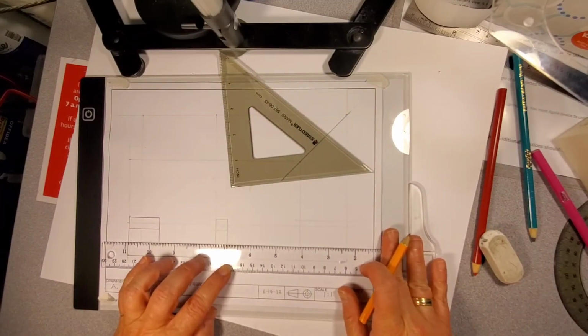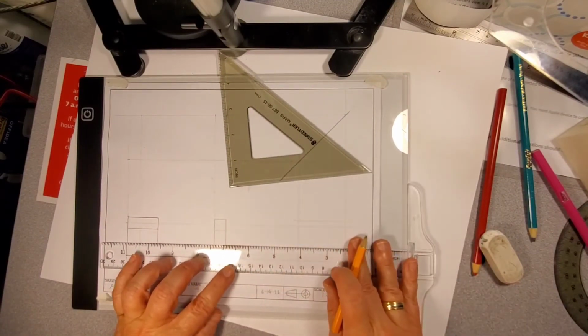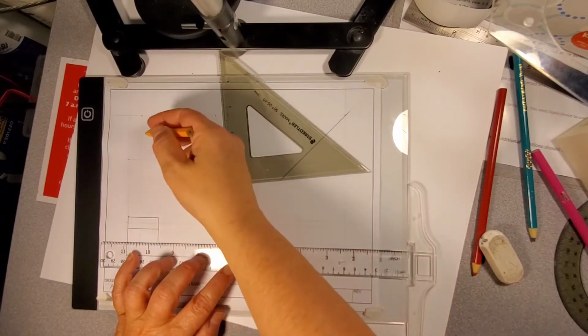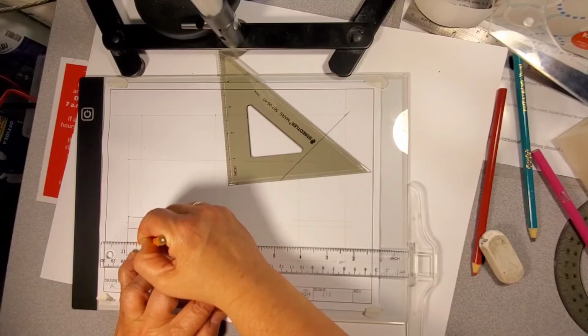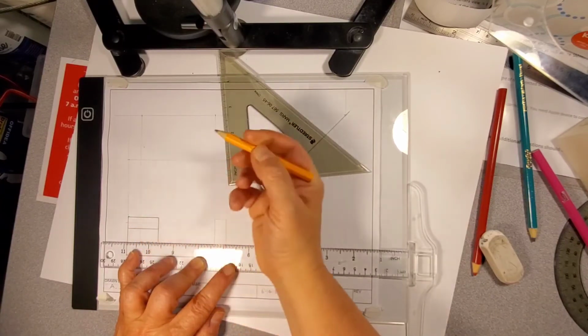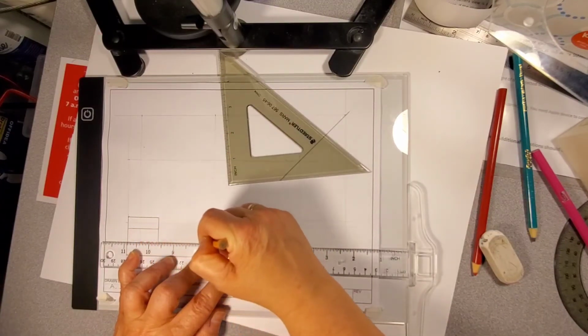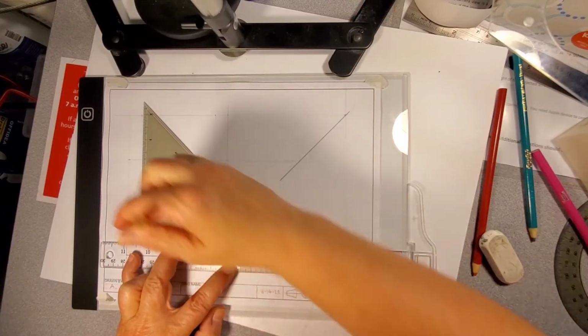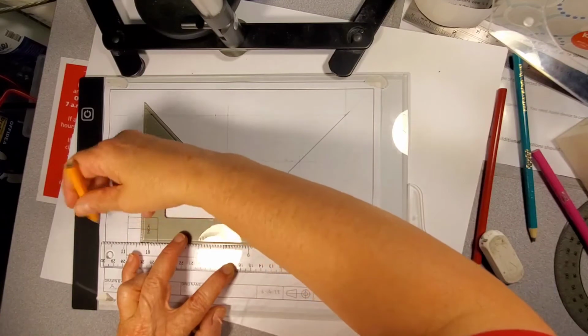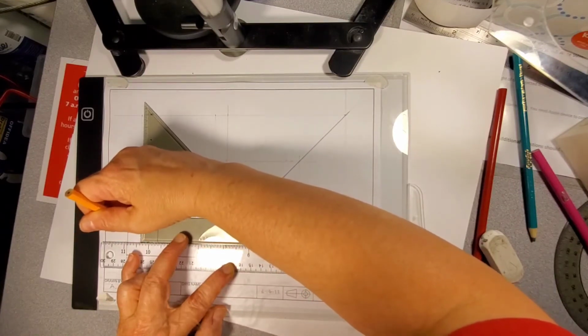Here's the bottom. But what do you know? You know on top that the back side goes all the way to here. So in here it's hidden lines, and then it turns into solid lines. And over here, this is hidden lines because it's behind everything. You can't see where it is.